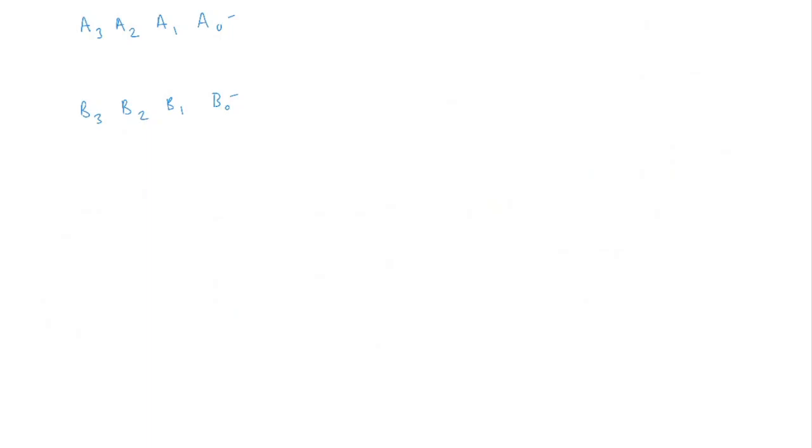So here's my subtractor. The inputs to this subtractor are A0 and B0, but this is not going to have any borrow in because there are no numbers on this side, and the difference here is just going to be D0, right? And it will have a borrow out, so let's call it B out 0.